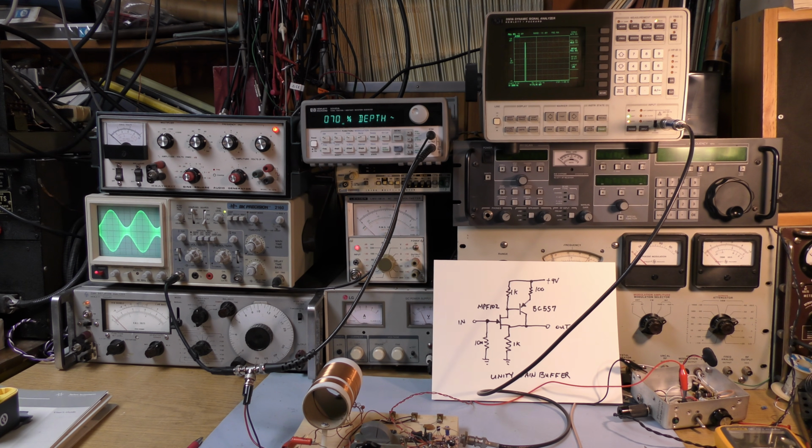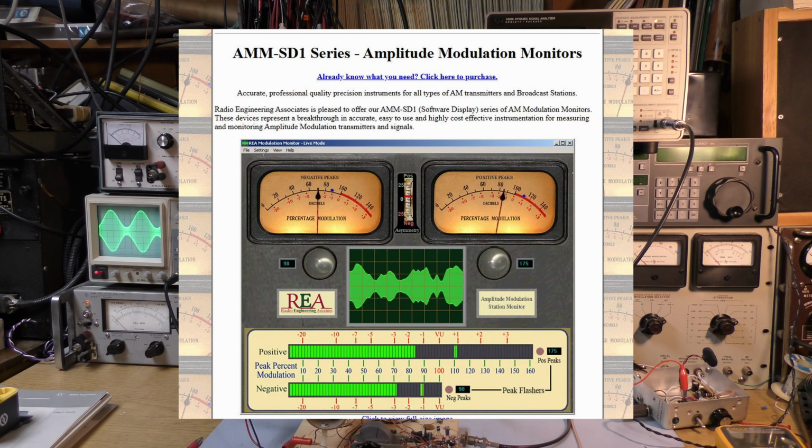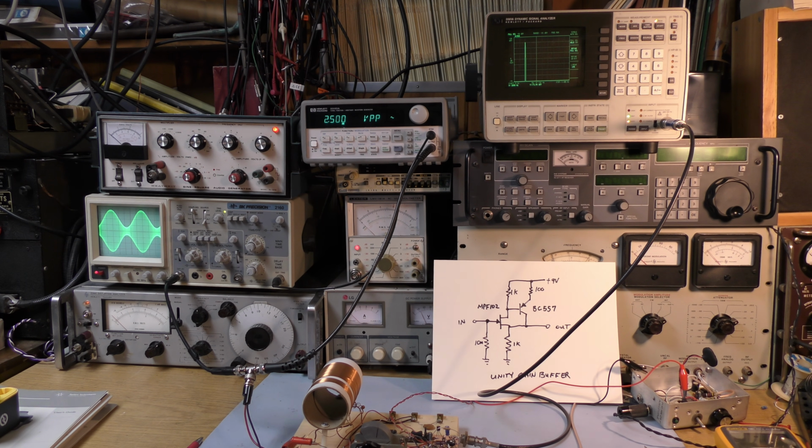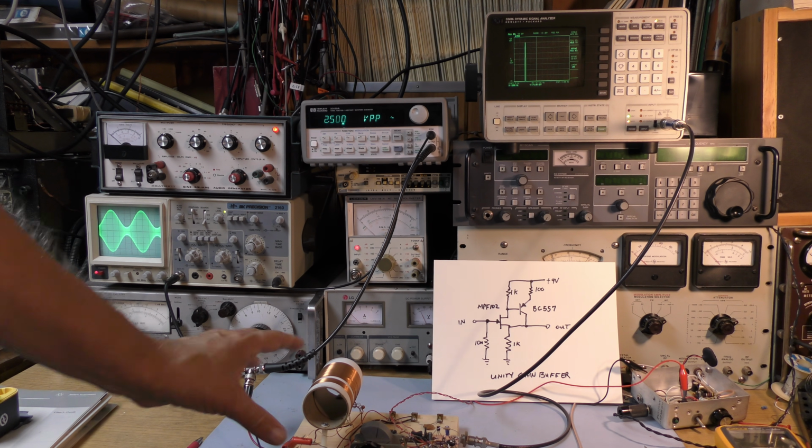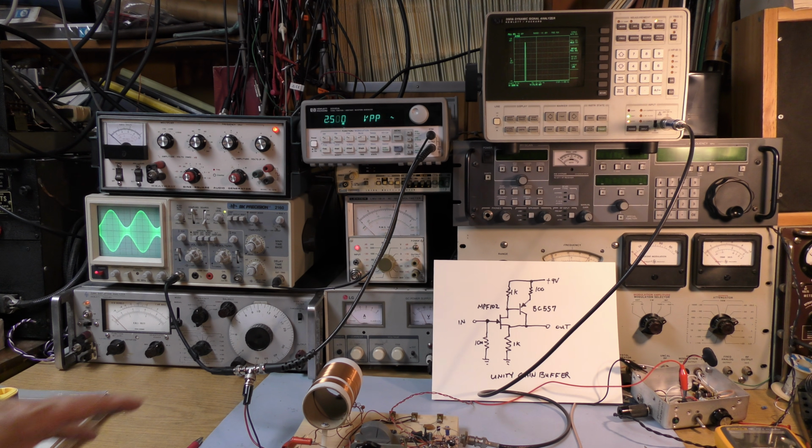The detector, when it's operating in peak mode, is very low distortion. And this is why Steve, WA1QIX, insisted that his peak measuring modulation monitor be fed a pretty high voltage, 2 or 3, 4 volts. That is what you want into his modulation analyzer. That's because he knows that his detector is going to have the least distortion when it's operating in the peak mode.